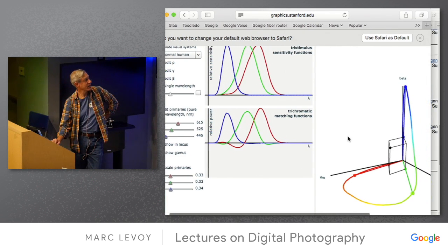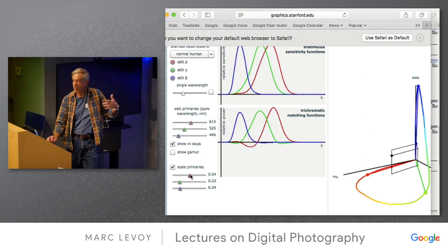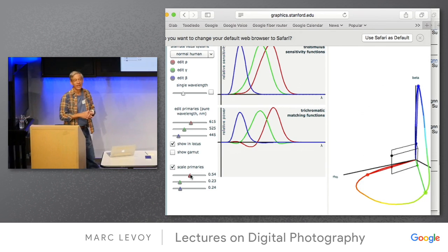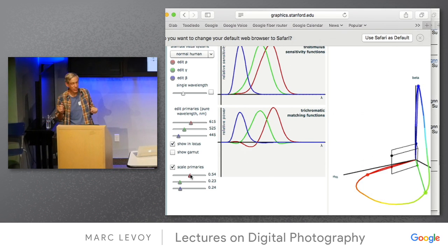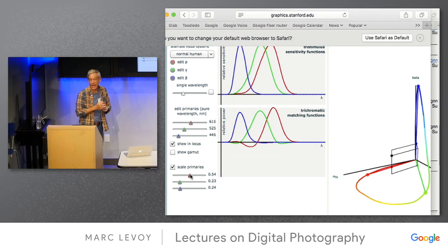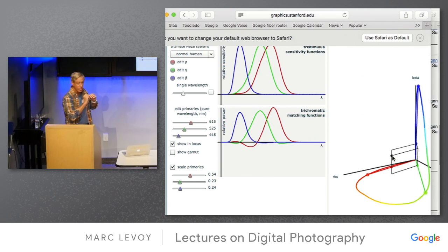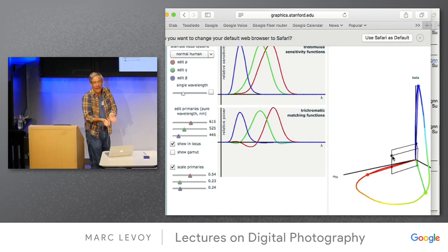What that scaling means is that we can set some arbitrary sliders on the strength of the red, green, and blue primary. Inside any old television set, there would be these dials you're not supposed to fiddle with that do that. We can think about that as setting the color of a reference white, which would have unit amounts of that red, green, and blue subject to this extra scaling.